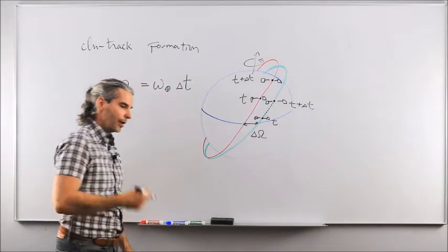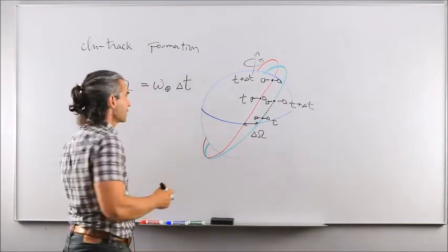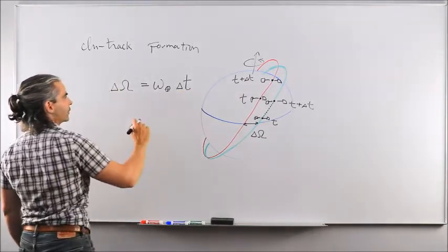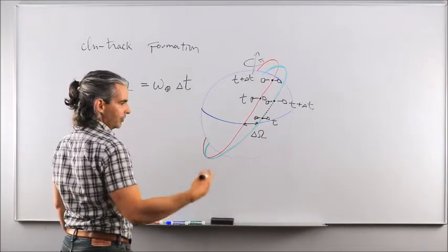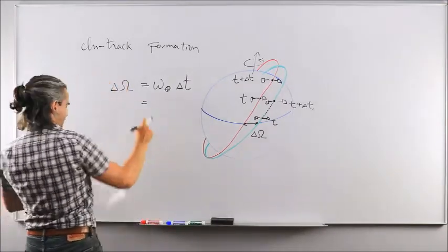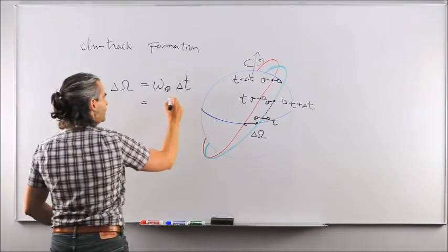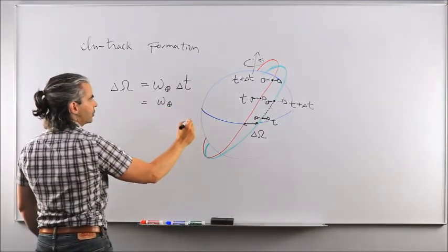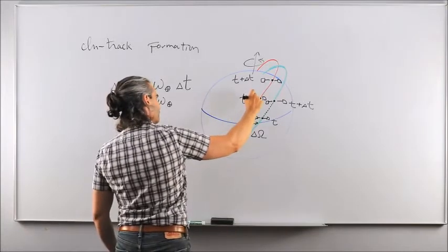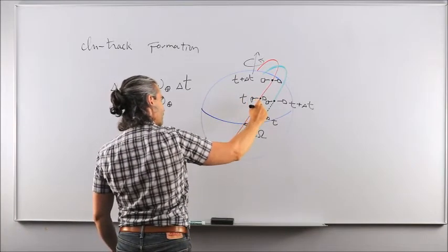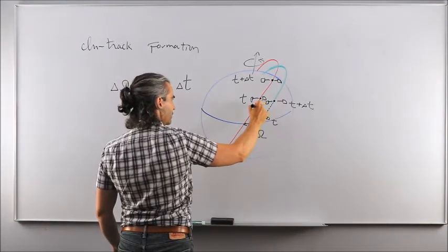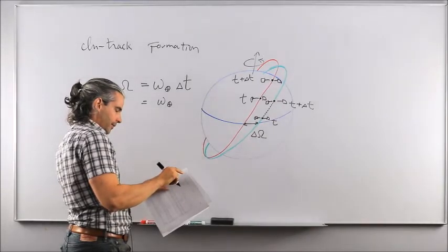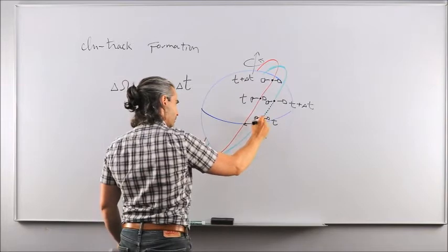spacecraft 1 flies over Ottawa, and 1 hour later we see spacecraft 2 flying right over us, or 2 hours, or 30 seconds, I don't know. That's the delta T you want for the exact same spot in terms of visibility from the spacecraft, okay? And this delta T could be translated into a delta true anomaly, okay? Because the perigee of both spacecraft would be a good idea to be located at the same spot in terms of the distance from the line of ascending node.